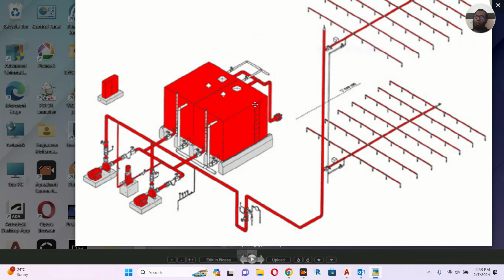And monitoring the tank, we need 2, that makes 10, and we need to know the level of the tank. And this breeching inlet is coming here. In case of fire, if the tank finishes, the people come outside with the firefighting truck, and they will fill the water through here, then this will supply water continuously.